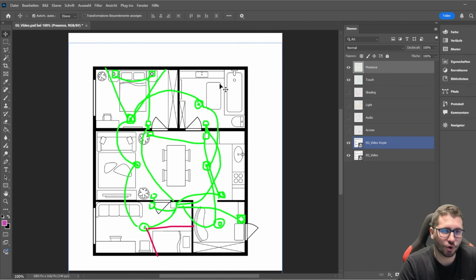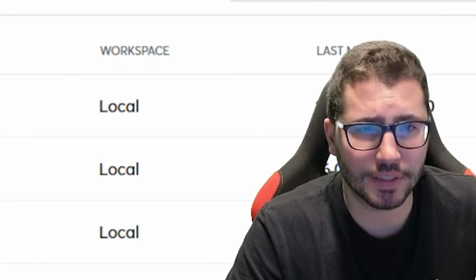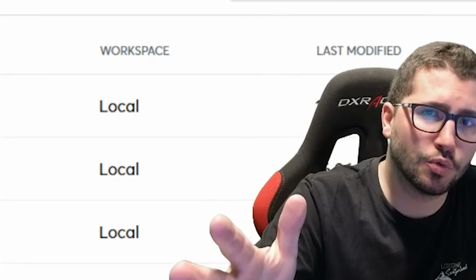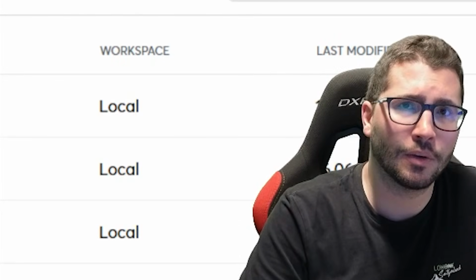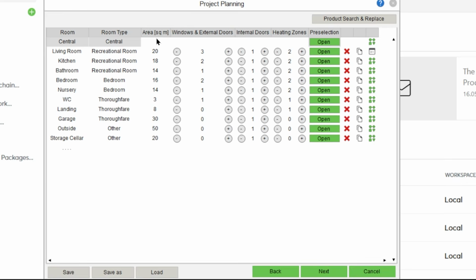So we would just go for all the rooms here. There is an outside room as well, and then we also put in the square meters or square foot, depending on the country you live in. This is taken for various calculations, like the flow temperature for underfloor heating. How big is the room which has requirement of temperature? Is it a small room, water closet? Is it a super huge living, dining area and kitchen? Just fill it out nicely.